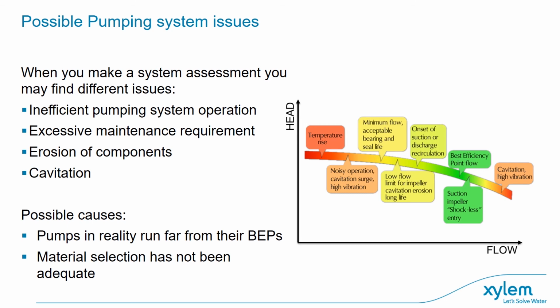Actually, backflow is one of the key elements through which each and every hydraulic can lubricate itself and all the rotating parts of the hydraulic itself. This must be granted on one hand, but on the other hand should be limited to the minimum.